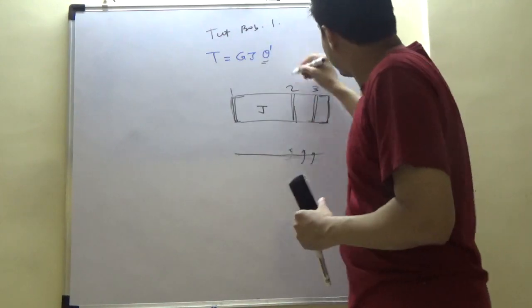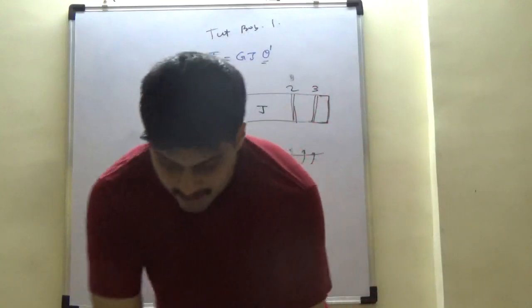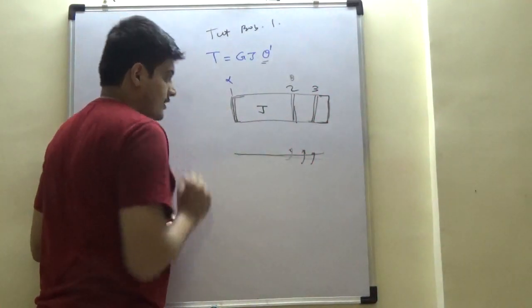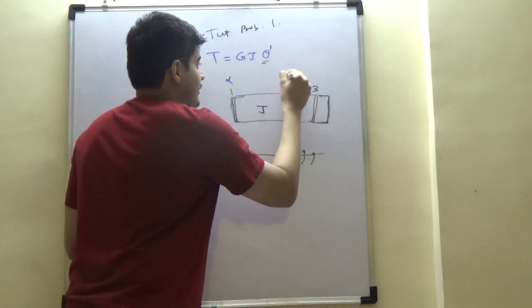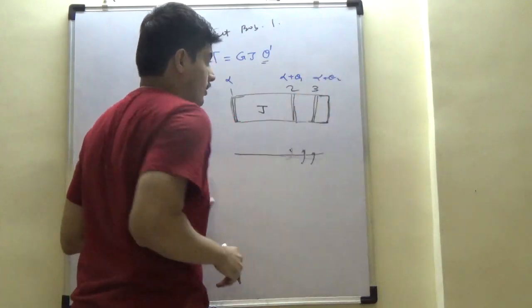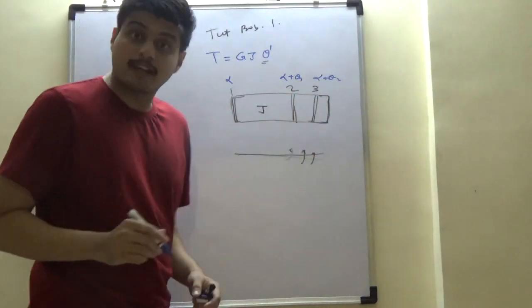These are going to form different angles of attack. My goodness, aerodynamicists suddenly have a worry. So at section 1, angle of attack is alpha. Then here it is alpha plus theta 1. Here it is alpha plus theta 2. So as the wing is getting twisted, it is actually seeing more angle of attack.